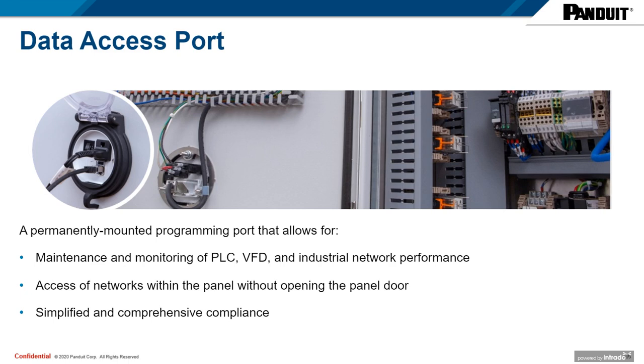Finally, for prevention through design and control panels, another device that provides a through-door interface to the equipment inside the enclosure are Panduit data access ports. These devices are permanently mounted programming ports that allow users to safely and securely access PLCs, variable frequency drives, and industrial networks within their equipment.